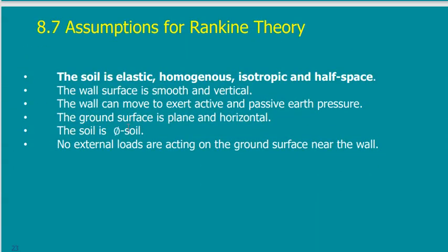The soil is phi soil. This is the most important. The soil is phi soil. It means that I cannot use this equation to solve a retaining wall carrying C soil. If you have clay and you have a retaining wall in front of this clay, you cannot use this equation, because it should be a phi soil, or in the worst condition a C phi soil.